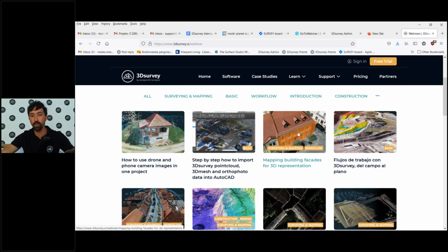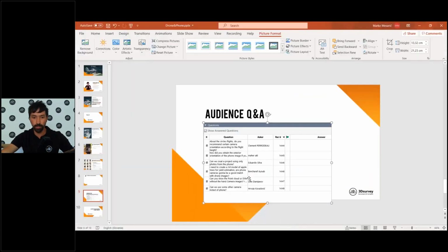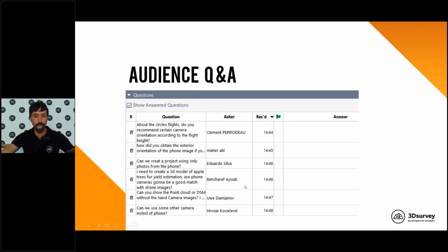See how I orientate the model based on 3 known points where I measure the dimensions with the measuring tape, and this will help you with the orientation of the model. But of course, take your phone camera and just do the mapping with it, and that's it. You can even film a video, extract the frames and calculate the model out of it. Don't forget, if you have a digital camera, use it, which is much better in comparison to a phone. The pixel number of the camera is not the most important thing. The sensor size, how big it is, is important.